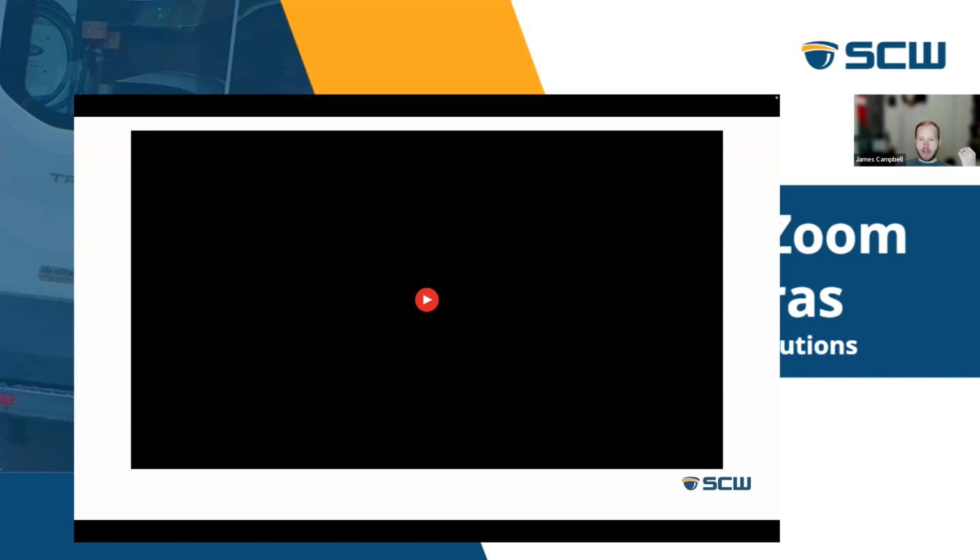When it zooms in and gets that face, we want that other camera that's looking at the fence to be able to capture the rest of the scene. So if they go off and do something bad, you've got evidence from two different cameras, one that's going to give you a nice clear look at his face, and the other one that's going to capture the scene. So that's the idea behind those functions, and that's why it's so important to have that cover camera on the PTZ.